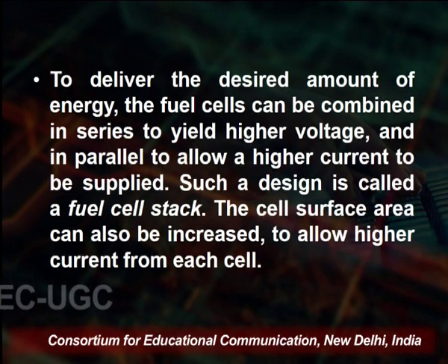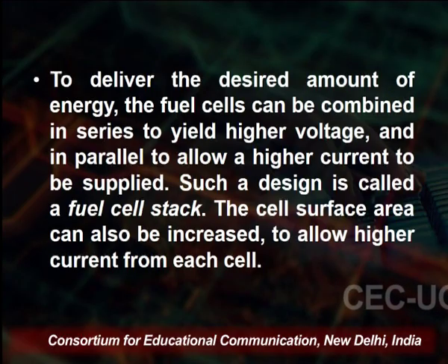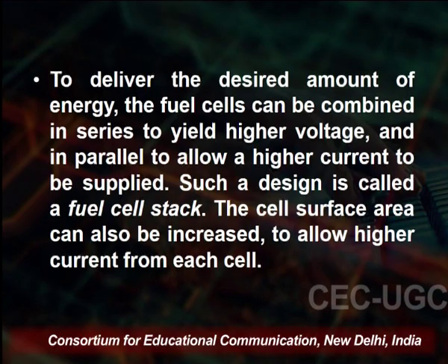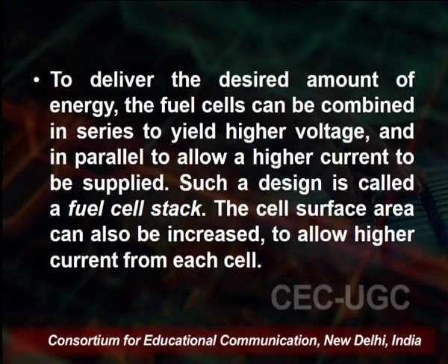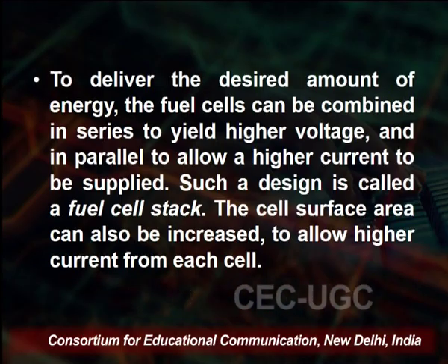So, to deliver the desired amount of energy, fuel cells can be combined in series to yield a higher voltage, and in parallel to allow a higher current to be supplied. Such a design is called a fuel cell stack. The cell surface area can also be increased to allow higher current from each cell. So, these are the features through which we can get high efficiency of the fuel cell.